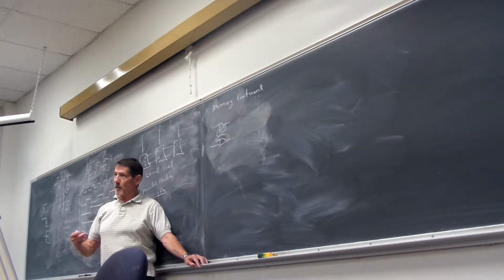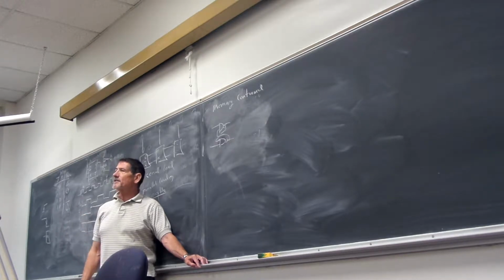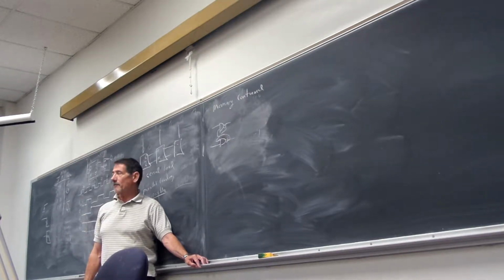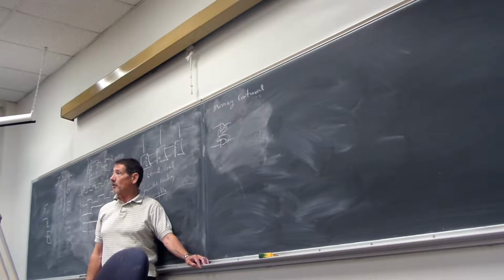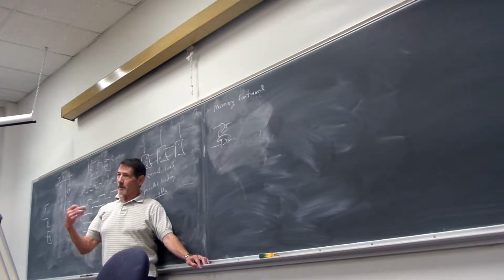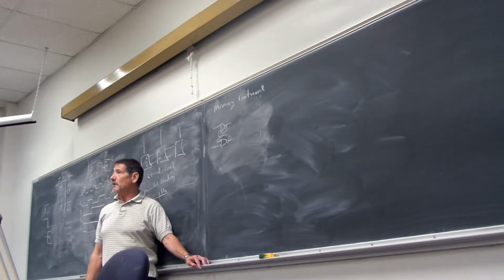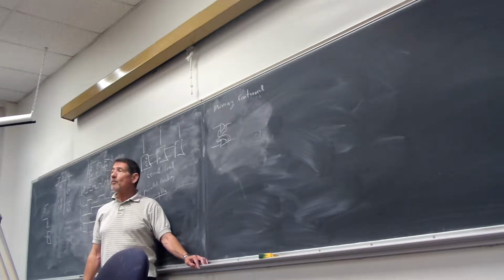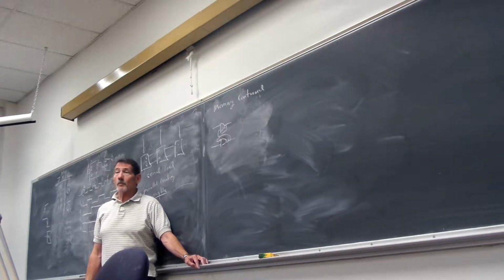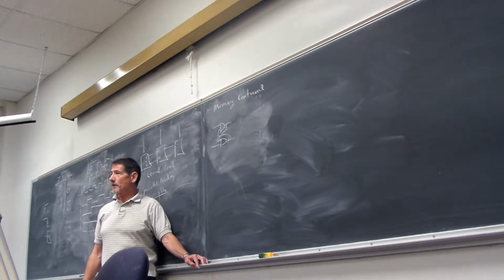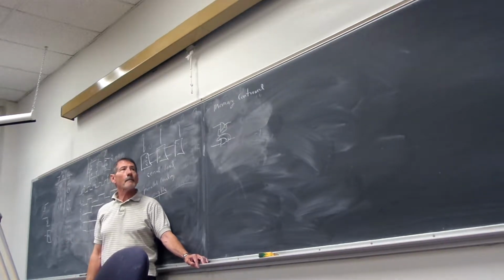So that in order to have it be kind of in a static situation, we'll have both the set bar and the reset bar lines high. In other words, a bar means that that variable is active. So we can store information here, and it will stay there for as long as we want, almost.